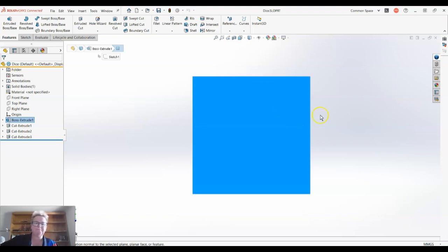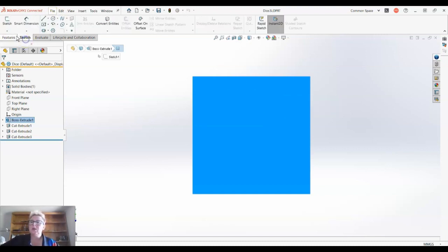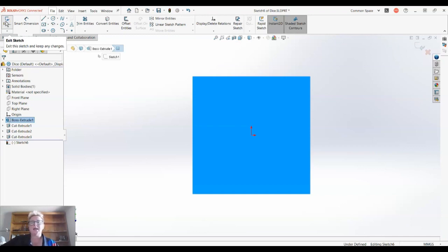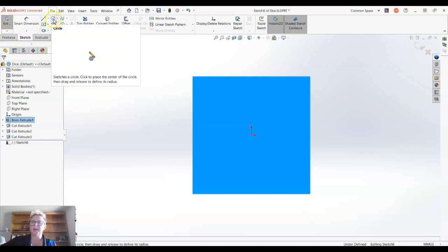It's a beautiful thing. Now this is selected obviously because it's blue. If I click out in the graphics area here, it goes grey, it's not selected, so I would get that yellow alert, not an error message, just saying, hey, tell me what you want to draw on. Let's just select that there. Then go up to my sketch ribbon and select my sketch button, and what did I say we were going to do? Number 3. So number 3 is basically one straight diagonal with 3 holes.